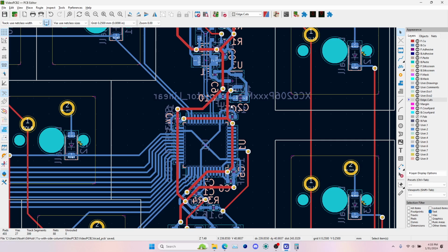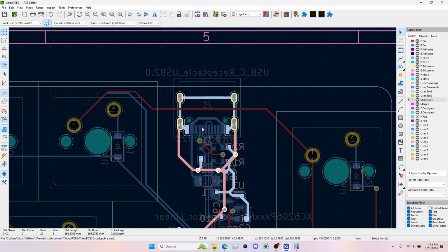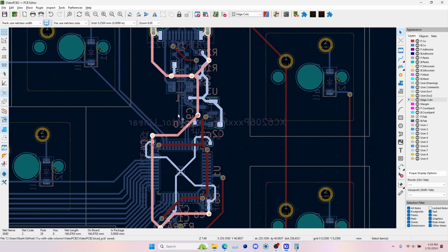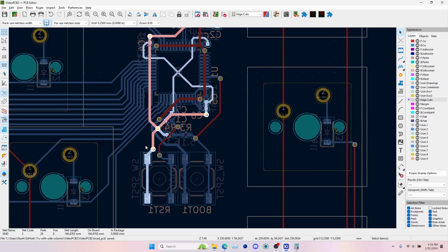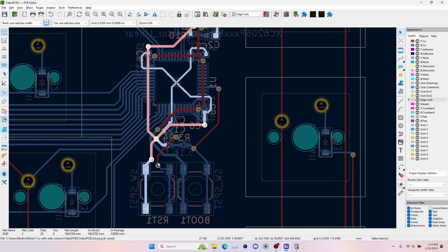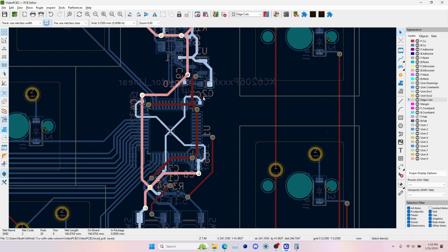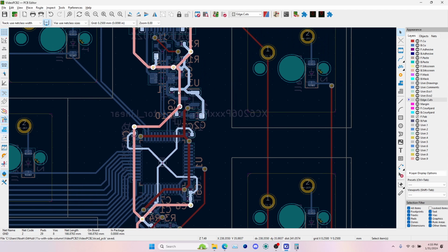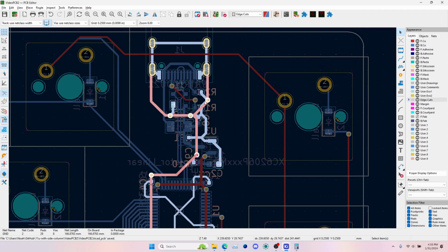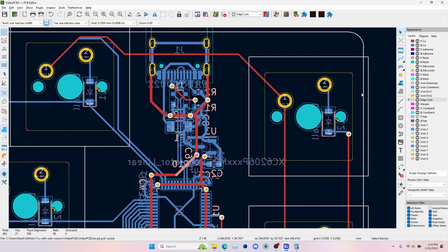And this, you know, with the template already having big ground traces, like this trace here is our ground net, right? So we have our ground going through the connector, and then this big red trace carries ground all throughout the whole thing. So it carries ground to the reset switch, it carries ground to the ground star that's within the STM. It carries ground to all of the capacitors around the filtering capacitors and decoupling capacitors, right?